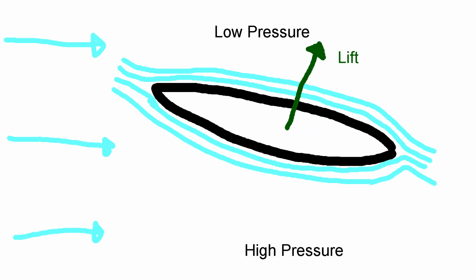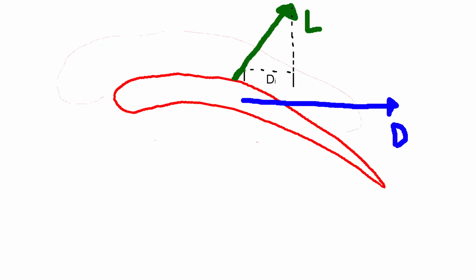Fluid dynamics. Lift. Lift is produced from the higher pressure below the wings and lower pressure above the wings. The pressure differential is created by shaping the airfoil and angling the wings down. Drag. Drag can be broken down into three main types: skin, form, and induced drag.